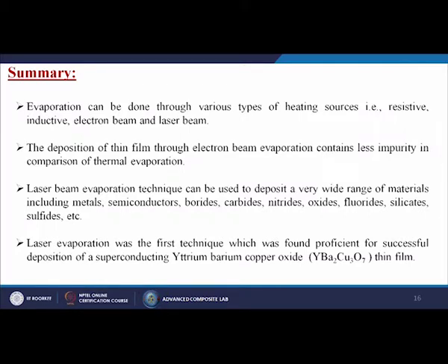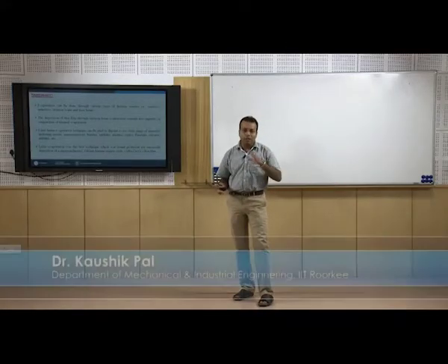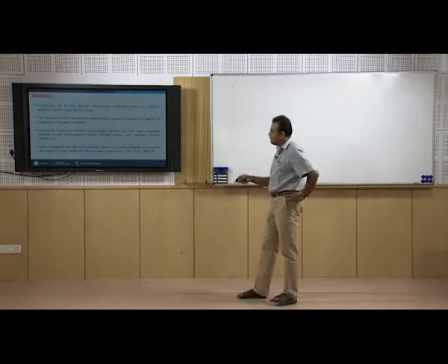Laser beam evaporation techniques can be used to deposit a very wide range of materials including metals, semiconductors, borides, carbides, nitrides, oxides, fluorides, silicates and sulfides, because the laser's heat energy is high, it can vaporize any kind of target material easily.